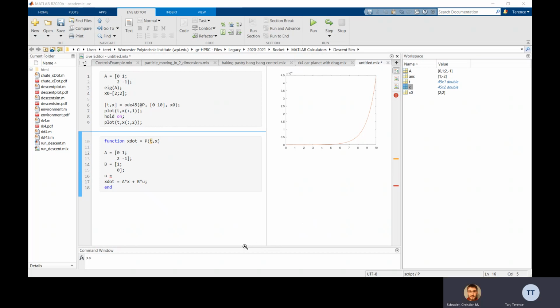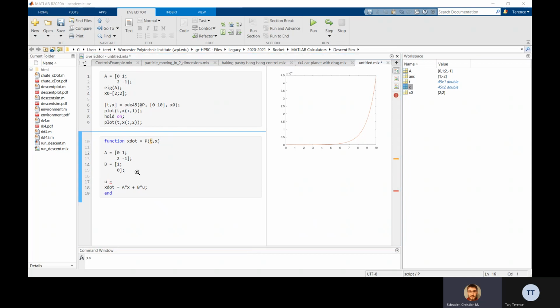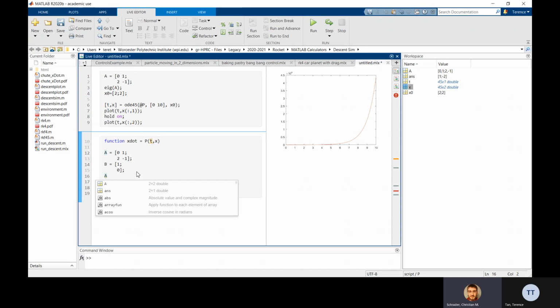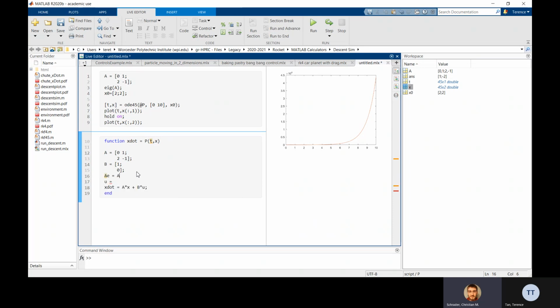Yes. And so if all of the eigenvalues of that effective matrix have negative real parts, that means your controlled system will be stable. And one thing real quick, this is a step you do separately beforehand.